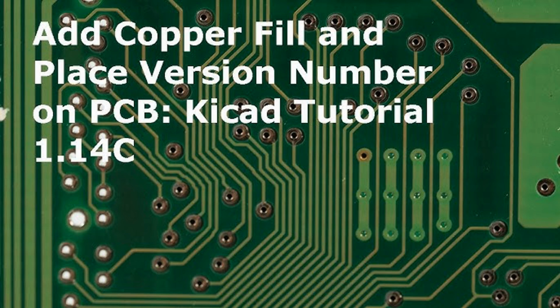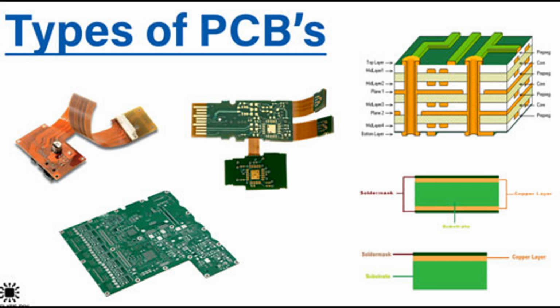Functions. Interlayer connections. Vias allow signals, power, and ground connections to pass between different layers of a multi-layer PCB. This enables complex routing and minimizes the need for long, space-consuming traces on the PCB's surface. Signal integrity. Vias play a role in maintaining signal integrity by providing a low-resistance, reliable path for signals to transition between layers. Properly designed vias help avoid signal degradation. Heat dissipation. In some cases, vias can be strategically placed to enhance the PCB's thermal performance by improving heat dissipation from components to internal copper planes.